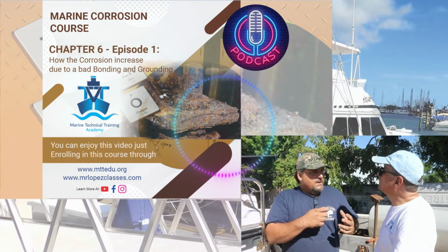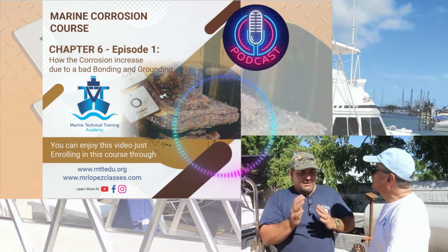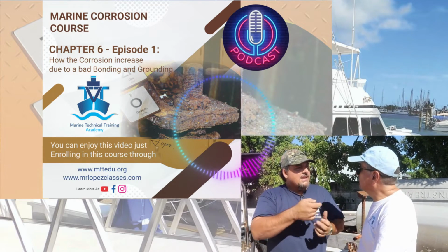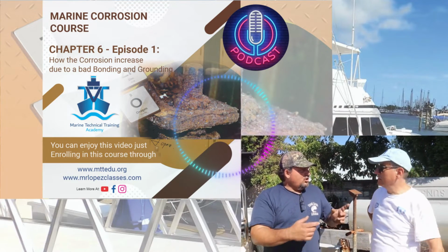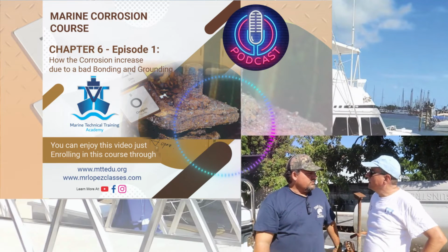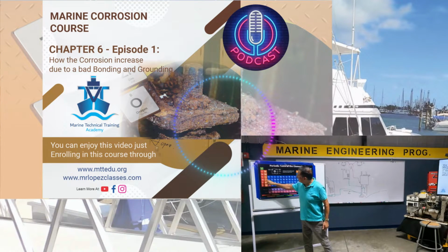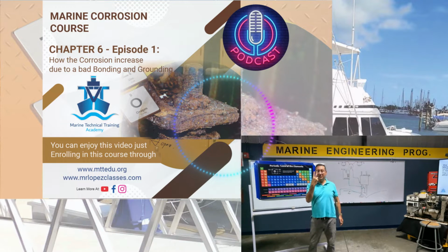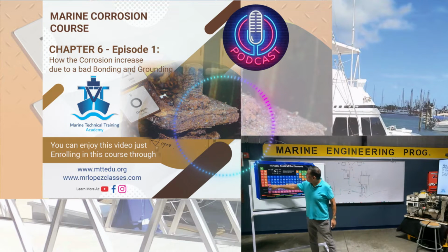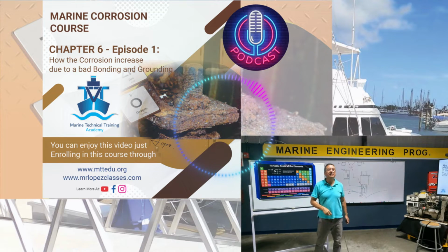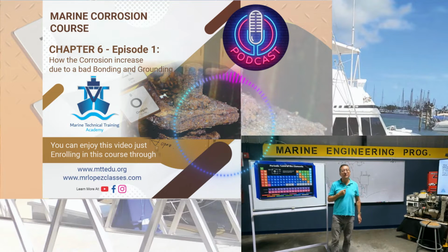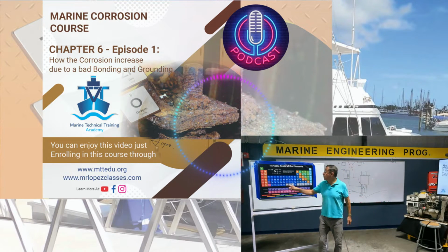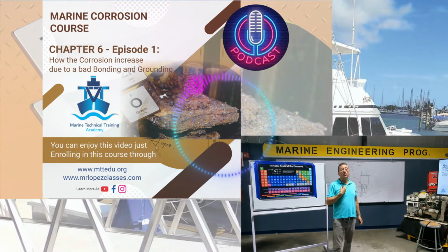If the metals are in direct contact with the seawater, there are a lot of factors that affect the acidity and the alkalinity, of course. The stray currents, which come from AC and DC, both of them. The cathodic protection, the sacrificial anodes, the permanent contact between the water and similar metals, galvanic corrosion, and the bonding system. That's important. Also, if the metal is not in direct contact with the water, it's affected.